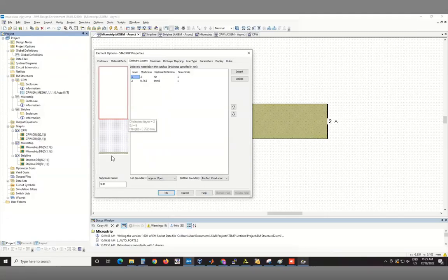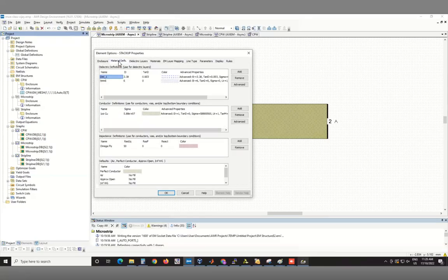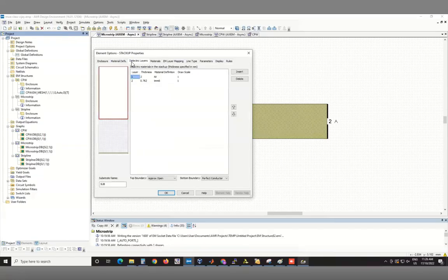Since this is a microstrip, we have a perfect conductor at the bottom, then the substrate, then some amount of air, 2 millimeters. Then we keep that as proximity. As I mentioned, the top boundary can make a difference if this thickness is very small, so the background plane is close to your active metallic conductors. In this case, it shouldn't really matter. And this TMM6 was defined here. Just a very quick reminder.